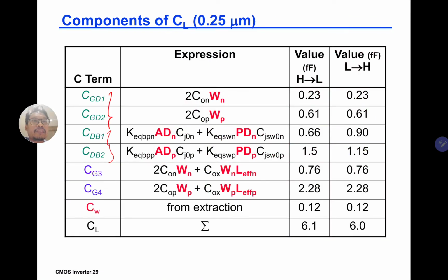Okay, so these are your intrinsic, and then here is your extrinsic, or the fan out or the load capacitance, and here is your wire, and then you have your total CL, the total CL on the load line. And here I think we've seen already in the previous notes, slides, we've seen the equations already, quite similar.